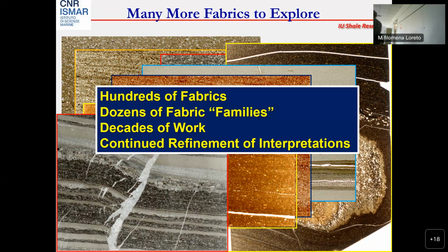The only problem is the flume channel is steep, and the sensor sits right here at half height. When you erode a mud bed, the first thing you generate is little lumps that travel over the bottom of the bed. They don't even make it up to here. So if they had looked, they would have seen all those little mud balls migrating around in circles and their bed being eroded, but it didn't register on their suspended sediment sensor.